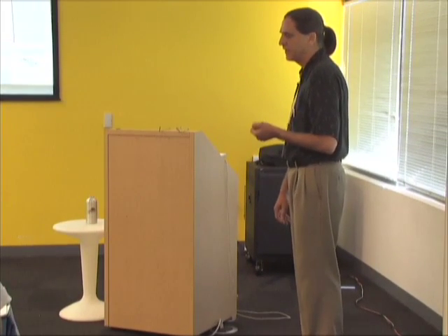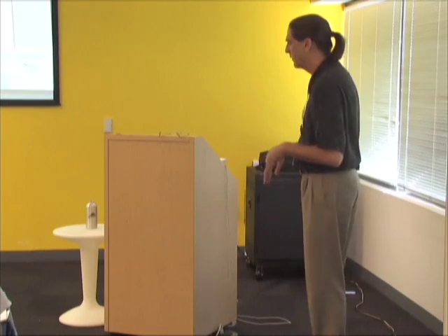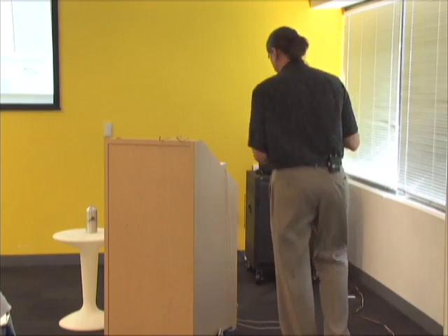I'm just going to talk for a second about creating these things. You really need to work at minimizing the file size. The biggest thing about the file size I find, and anybody who wants to chime in is welcome to, I don't find the file size affects how working with the model is, but it really affects how long it takes to load the model. I don't know how many people have been giving a presentation and they had their backup set at 5 minutes and they have a large model, and all of a sudden they go to move the model and the little hourglass comes on, or the Windows rainbow of death, and you just sit and wait. So making it smaller will make it load faster. It just makes all the file transactions easier.